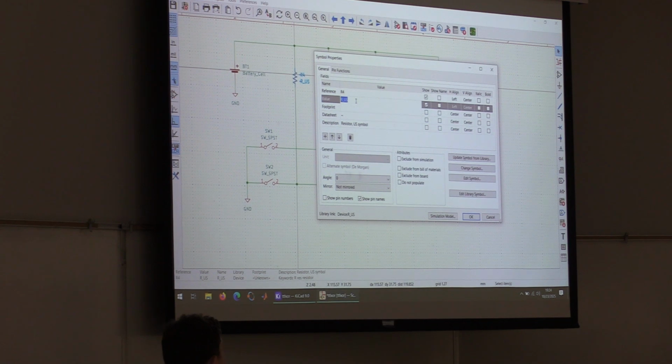Now let's give these components values. Following along with the schematic, these resistors are going to be 10 kilo ohm. And so we don't fill up a bunch of space with extra zeros, we'll actually use the SI prefixes at the end of the numbers. So a 100 ohm resistor you could write as 100. Some people use 100R. The R is meant to replace the omega symbol.